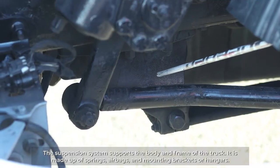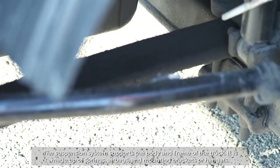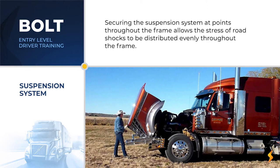The suspension system supports the body and frame of the truck. It is made up of springs, airbags, torque arms, and mounting brackets or hangers. The front and rear axles are attached to the suspension system and the frame rests on it. The suspension system allows the axles to move up and down in response to ground changes without seriously affecting the load.